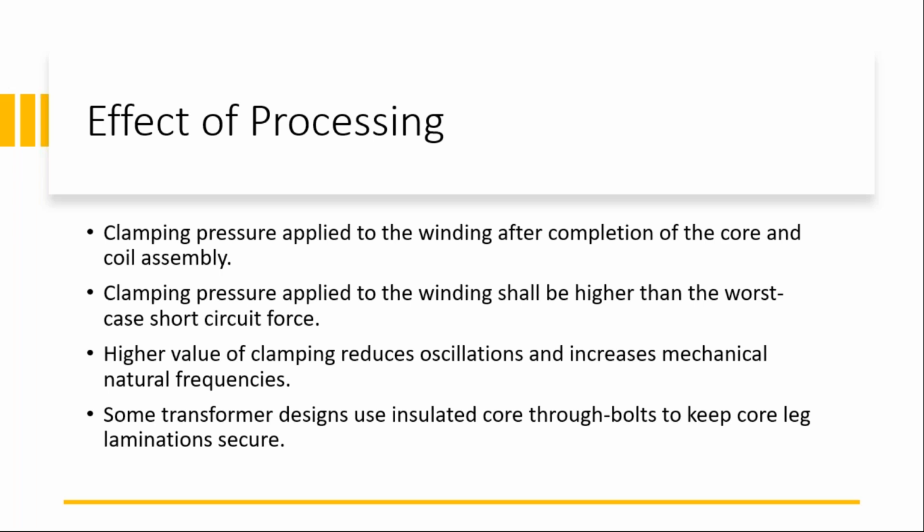Then, depending on the type of design, engineering gives us the force which has to go onto the coils to limit the oscillation. They also watch for any vibrations coming closer to the natural frequencies, and those are all taken care of in the design itself. One more thing is that some power transformers use insulated through bolts for the core yokes, just to give added strength.